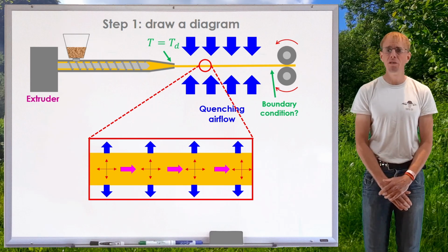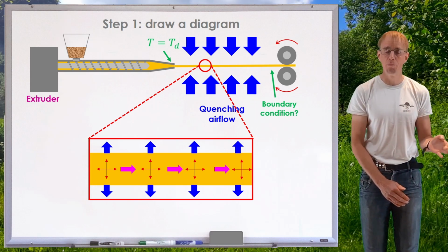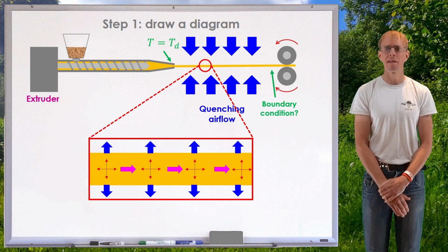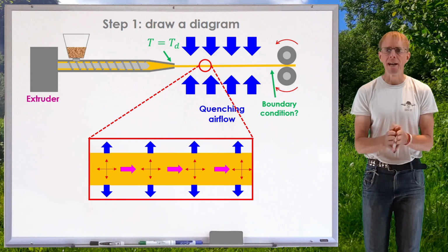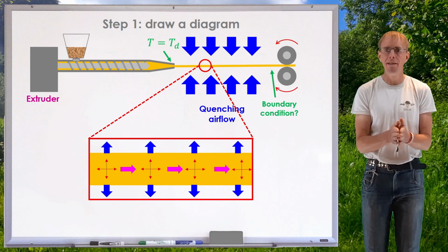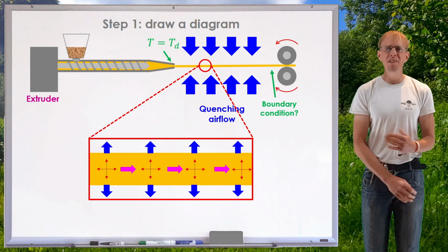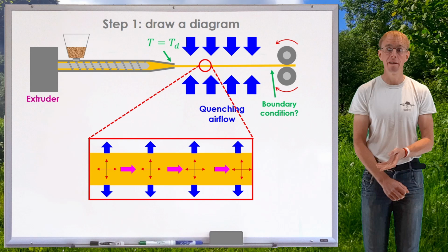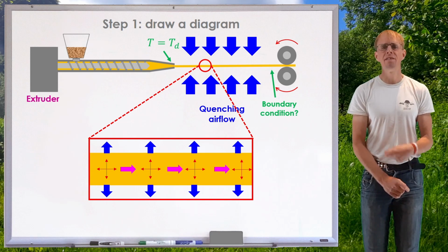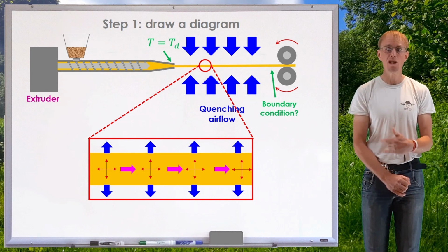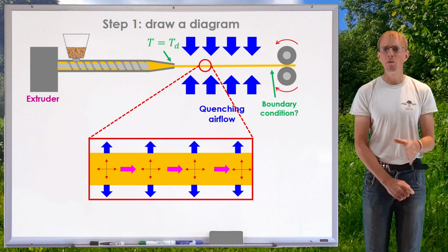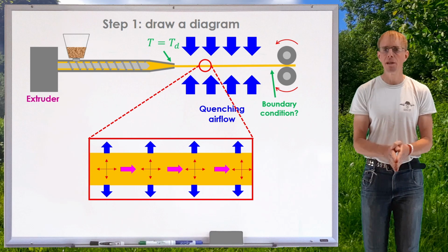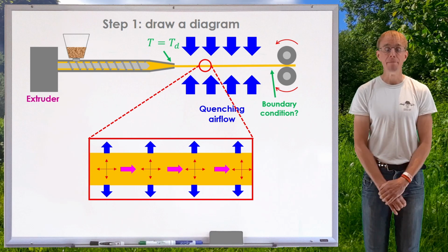So what could be going on? I could say that there's been enough heat transfer or sufficiently little heat transfer occurred for there to be effectively zero gradient happening there. It's like saying that at that point the film is insulated in my movement direction. It's not an ideal boundary condition, but at least it allows us to figure out what a temperature profile could look like. In reality, what's probably going on there is going to be a heat flux in the advection direction potentially, and we might need to estimate that. But if we estimate that there's zero heat flux to start with, it gives us a pretty good picture of what our worst case scenario is likely to be.